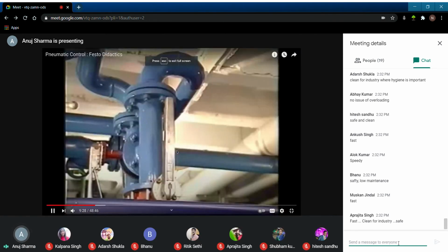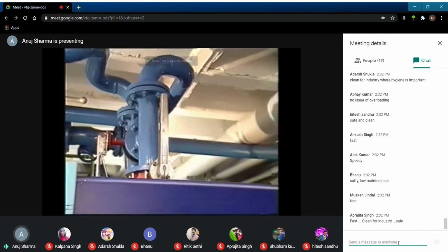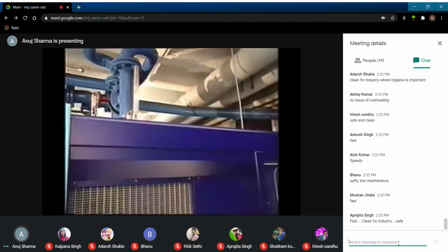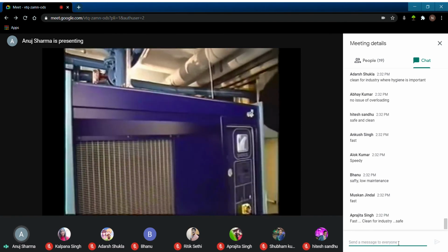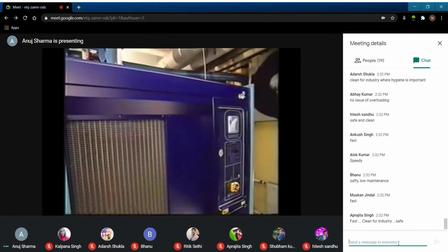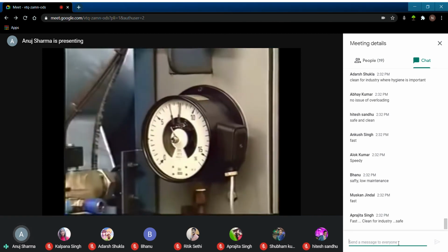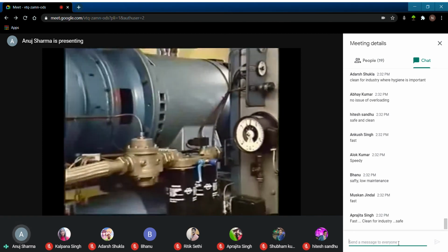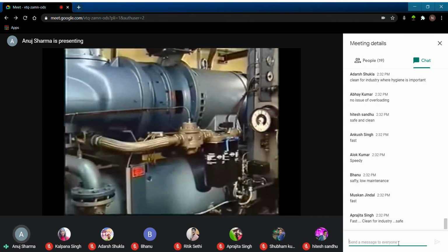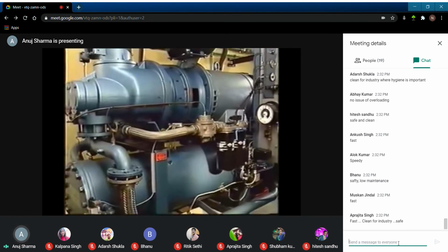Not all of the moisture is removed in the reservoir, so in order to prevent corrosion of valves and other components, a dryer is often included in the system. When designing and installing a compressed air system, the distribution of the air has a major effect on system performance.